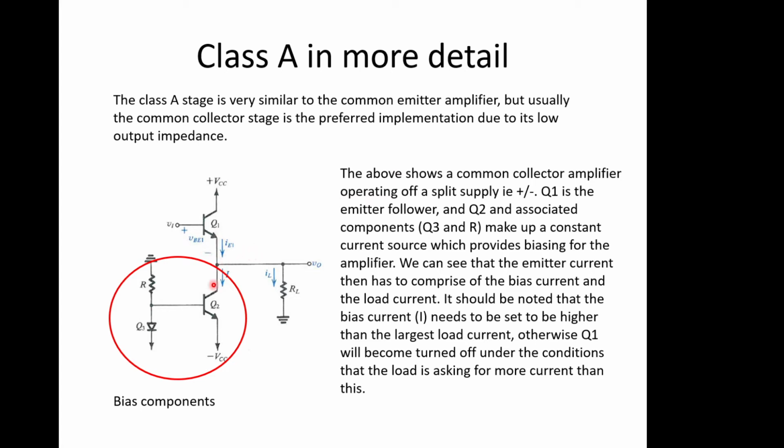It looks like there are two transistors here, but really this one is just providing the bias. Because there's a fixed current going through this diode, that provides us with a fixed voltage across this point. And if you've got a fixed voltage across this, the VBE of the transistor, then the transistor will provide a fixed current. So this is just a current source, a crude current mirror.